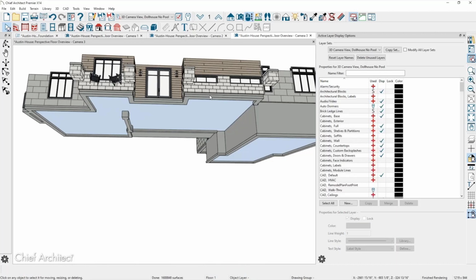Well, usually I'd have to take a look at it. Usually what I would do in the room definition is set that to be a porch and build it. When you build your foundation, then if it's set to be a porch, it'll come in at the same elevation as the rest of your slab. Well, unless you lower it. And I've done that. I just didn't, in this case, want a footing out where these columns were because it wasn't necessary, because that's what's going to carry the load of the roof.